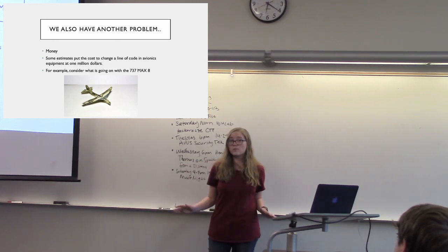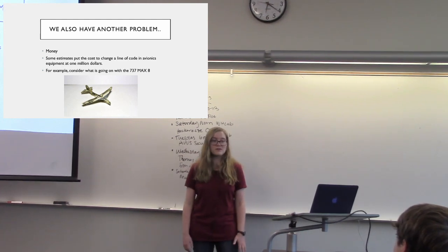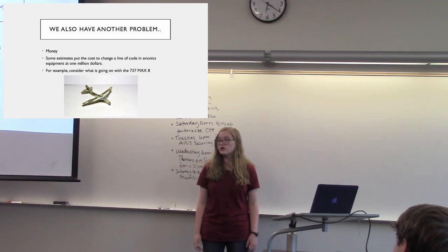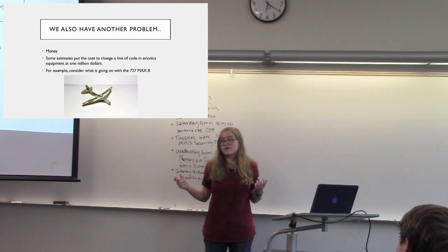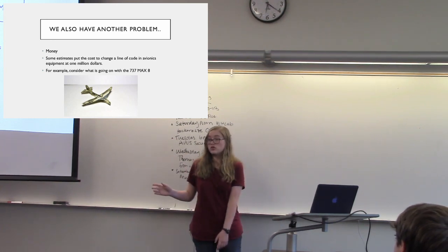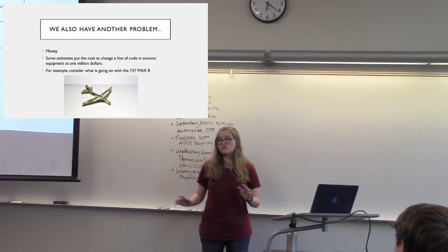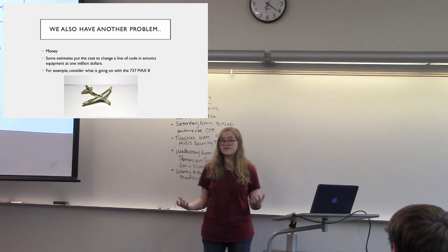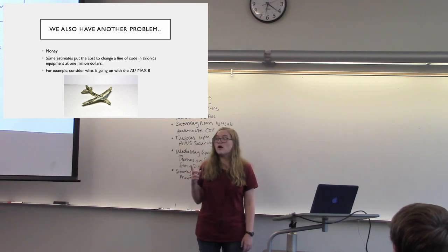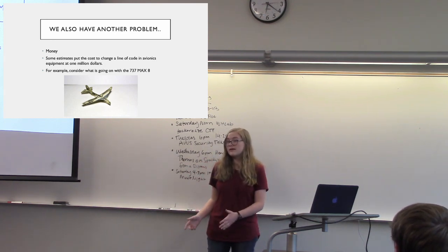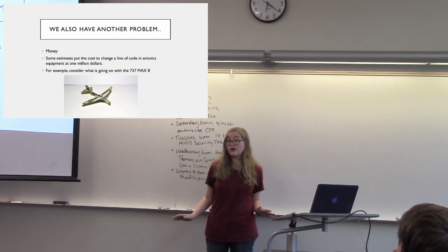going on. They had to ground all the planes because of an issue in the MCAS, or maneuvering characteristics augmentation system. This system is in charge of, if it thinks the plane is at risk of stalling, pushing the nose down. Originally, it took data from one sensor and made that calculation, but now in the new software, they have to take data from two sensors, compare it, not do anything if the difference in angle of attack is very severe, and then whatever change it makes cannot be more than what a pilot controlling the plane can recover from in case it's incorrect. And so those are the general software changes they've said that they're having to make.